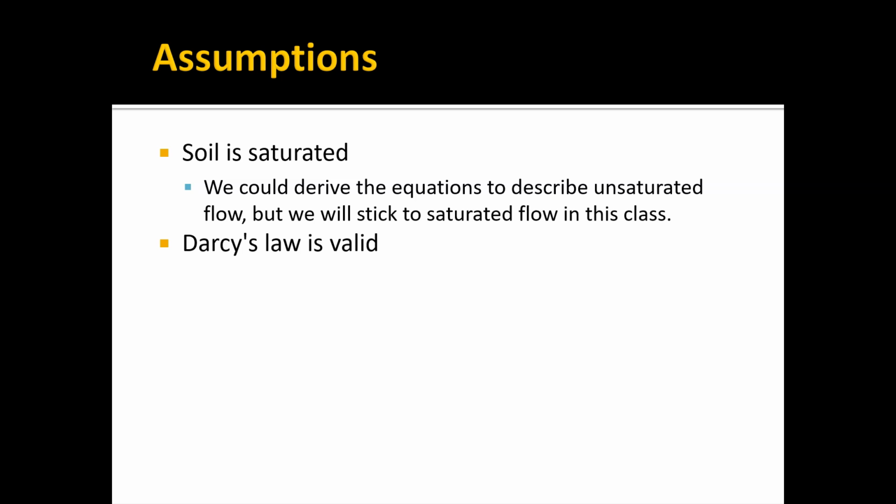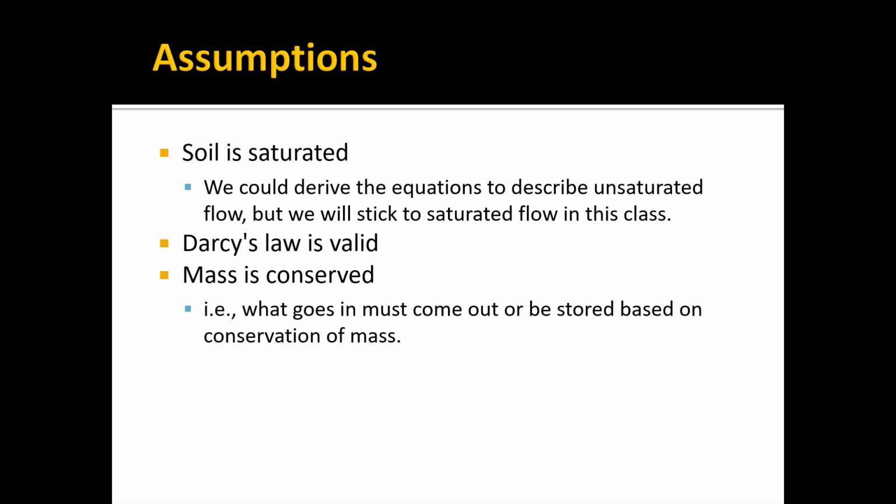We're also going to assume Darcy's law is valid. That's a critical part of this derivation. And another critical assumption is that mass is conserved. What goes in must come out or be stored based on a conservation of mass. Specifically, this is kind of the general form of the governing equation.